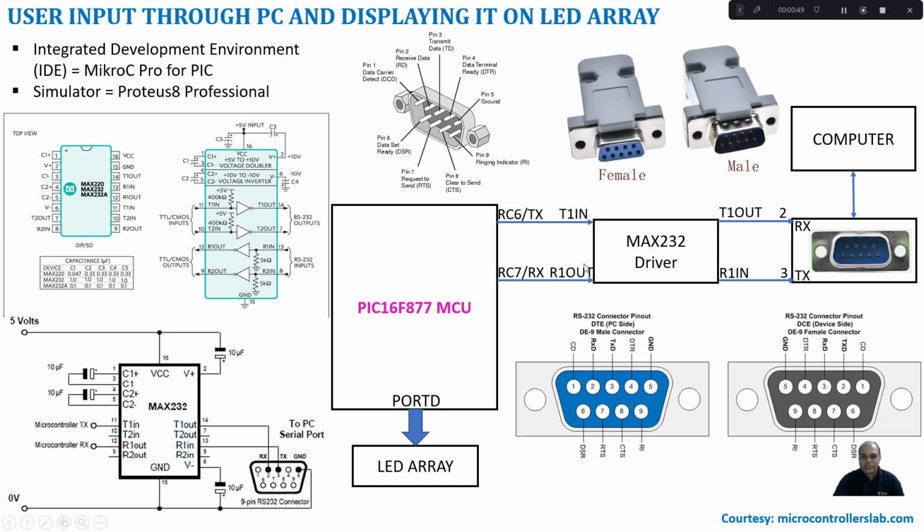This MAX232 driver is used for two things. One is it will double the voltage, and also it can be used as a voltage inverter. Why is this done? The PC works with different voltage ranges than the microcontroller. The PIC16F877 MCU works with TTL logic.